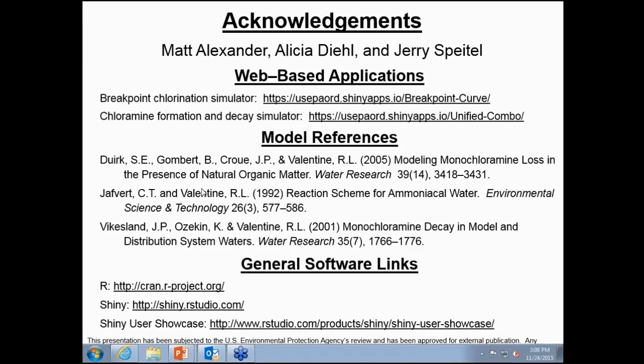Definitely all aspects of residual control, whether it be backwash water or spent GAC or spent ion exchange resin, and you generally get a choice of maybe 8 or so different options of what you would do with that waste. And it also is dependent on size and whether or not you have tanks to hold the backwash and issues like that. So it's definitely included in the model.